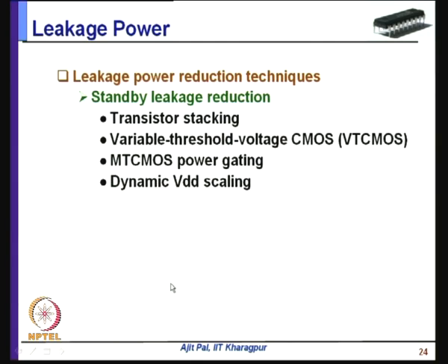Now, coming to the leakage power, so far we have discussed techniques for the reduction of dynamic power. The leakage power reduction techniques can be broadly divided into two categories: standby leakage reduction techniques and runtime leakage reduction techniques.